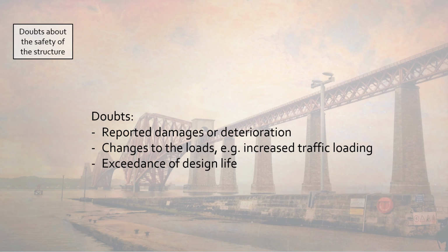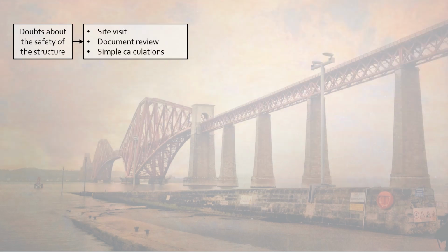In the case of Bakke Bridge, we can definitely say that it has exceeded its design life. When we have decided that an assessment is necessary, the first step of an assessment will typically be a site visit to the structure to perform a simple survey and or a review of documents related to the structure, such as design reports and drawings, to establish the design basis and the original state of the structure.